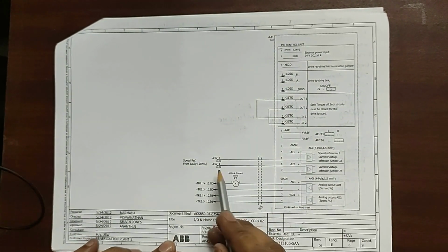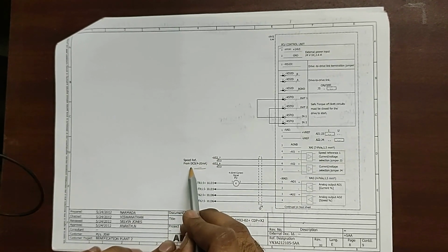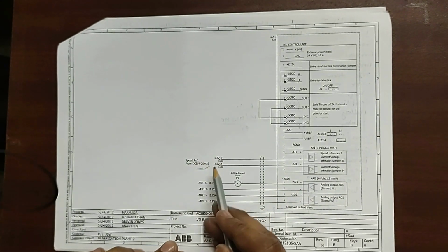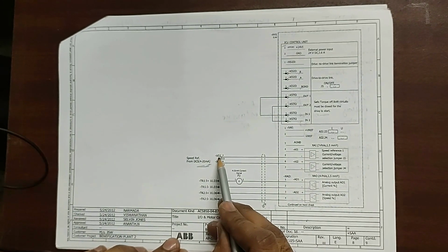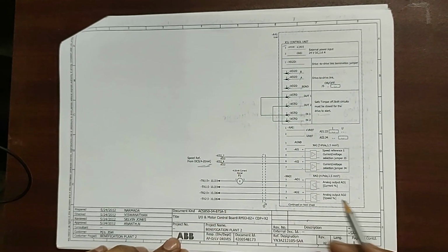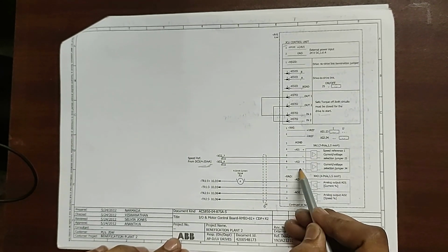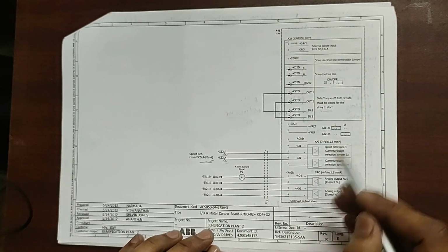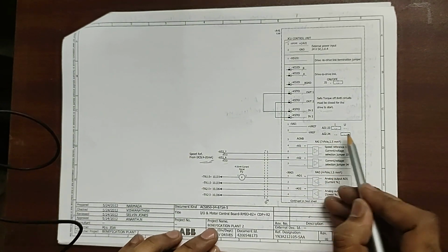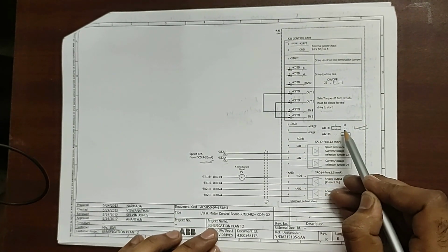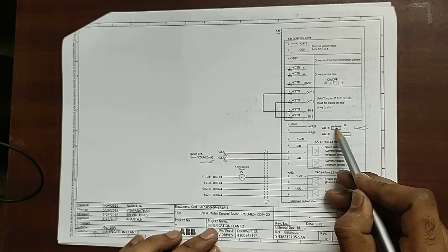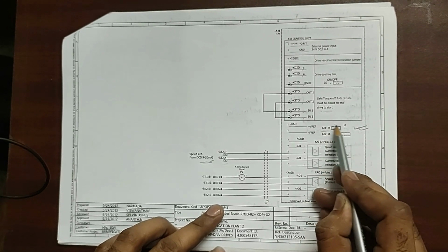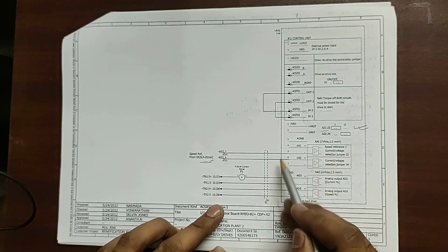And if the drive is running from remote, the reference from DCS is 4 to 20 milliamps. Why 4 to 20? There is a separate video on this. Why not 0 to 20 milliamps? You can go and see it there. And X52 7 and 8, page number 16, you already know. It will feed analog input 1 or analog input 2, whichever is required. If you change this, you have to change the setting in parameters also. And this is a very important jumper, whether you are running with current or voltage. This is current, this is voltage. Since A1 is selected here and the jumper is here, it will run on analog input 1 with current reference.